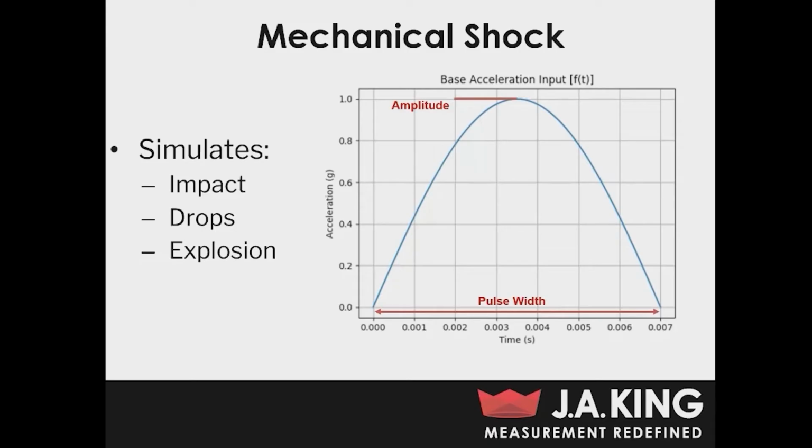And when you perform shock testing, each component of what you're testing is actually going to quiver at its own natural frequency. You can see here I've included a figure of a half sine pulse, and I've pointed out some of the key parameters here. You can see there's the amplitude pointed out there at the top of the curve, which is the acceleration level. And then I've also pointed out the pulse width, which is another key parameter. And that pulse width is essentially just the actual duration of the test itself.